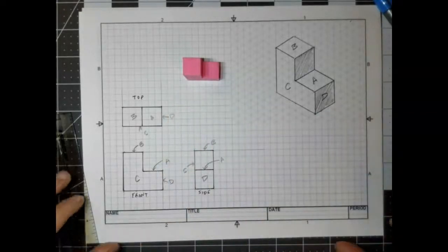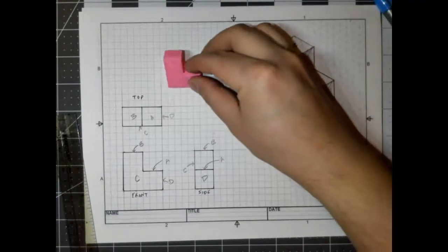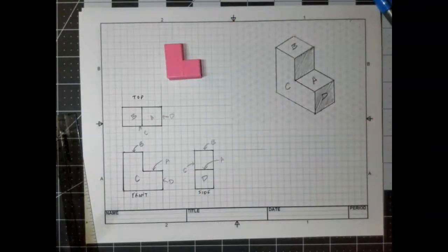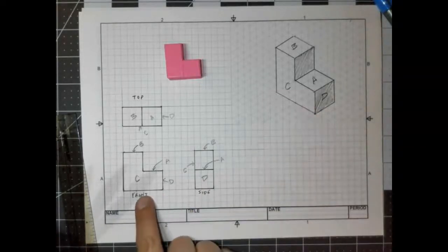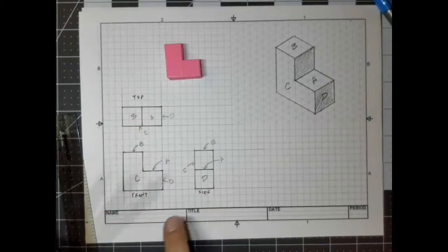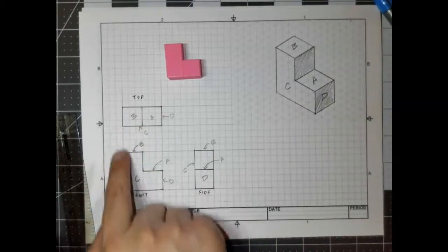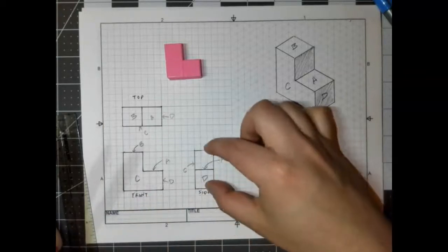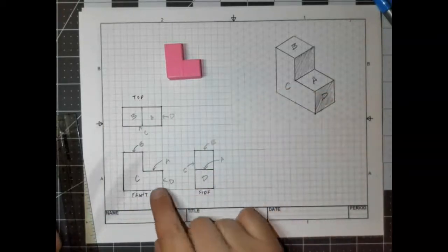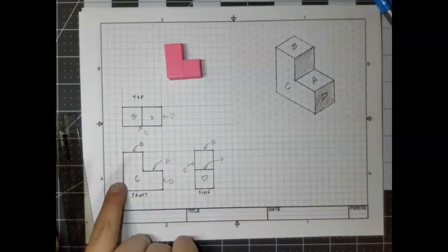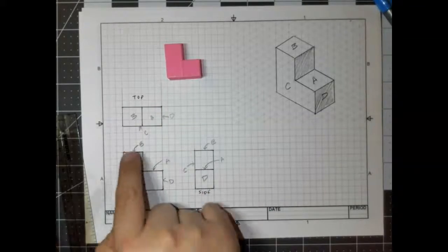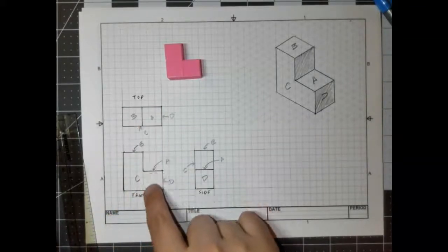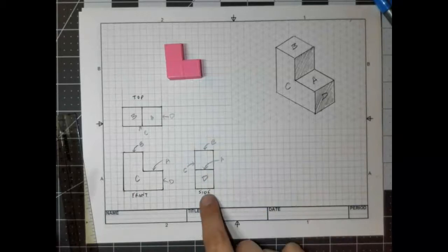So hopefully by this point you understand the basic concepts of drawing a multi-view drawing. You have an isometric view of the part, you have the front, the top, and a side view of the part. All of the parts are aligned, so if you drew your part and it's shifted up, that's incorrect. Same thing with the top view. If you have your back edge here aligned, that's correct, but if it's shifted over, that's wrong. So if this is 6 wide, it needs to be 6 wide in the top. If it's 6 tall, it needs to be 6 tall on the side.